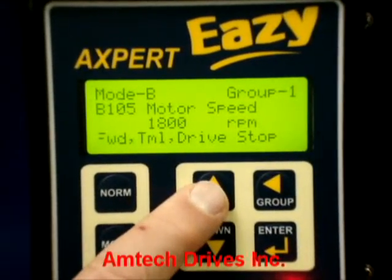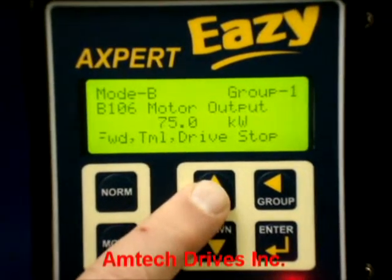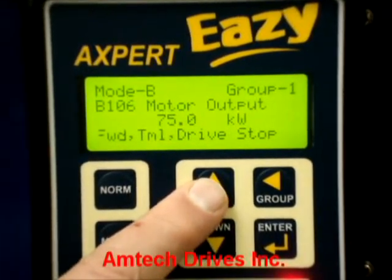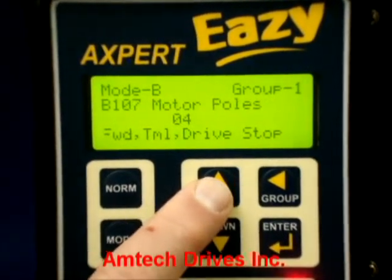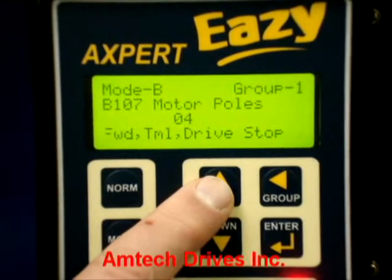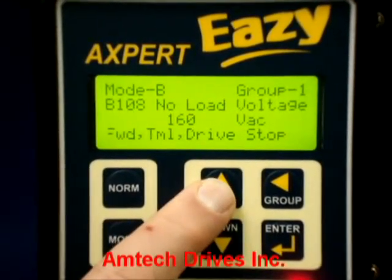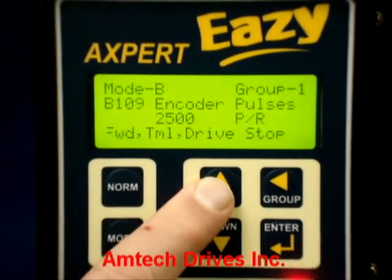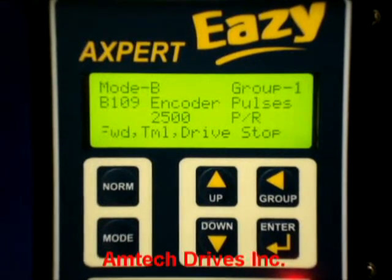The motor speed, in this case, set for 1800 RPM for a 4-pole motor. B106, your output, which in this case is a 75 kilowatt or 100 horsepower drive. Number of poles, again a 4-pole motor, 1800 RPM motor. And your no-load voltage when you're running in vector mode. And the encoder pulses. If you have a closed-loop system, you can set the number of pulses per revolution out of your encoder.